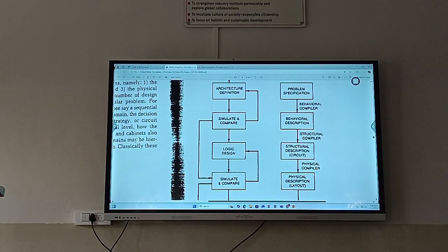Place the PMOS in parallel, then the NMOS, and below it another NMOS in series. Then its output on the right side goes to another PMOS and NMOS, so that the output of the NAND goes as input for the inverter. Totally I get the AND. This is the structure.